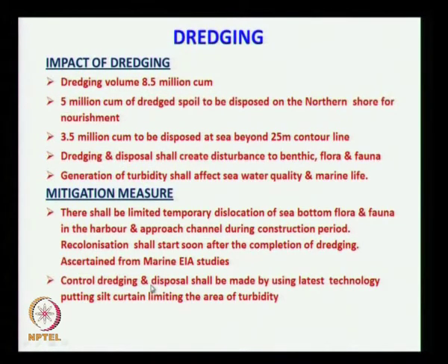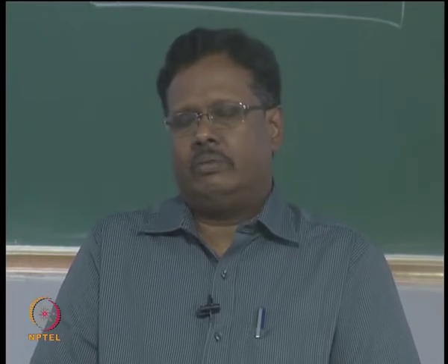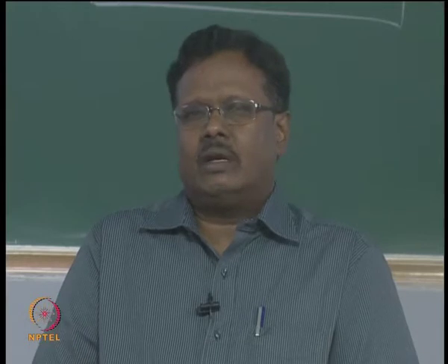And when you are depositing 8.5 million cubic meter at 25 meter water depth over an area of about 3 kilometer by 3 kilometer, the bed level shall not increase more than 1 foot, that is 0.3 meter, because we are removing the soil and putting it at the 25 meter contour. The water depth shall not vary too much. So that also you have to see.